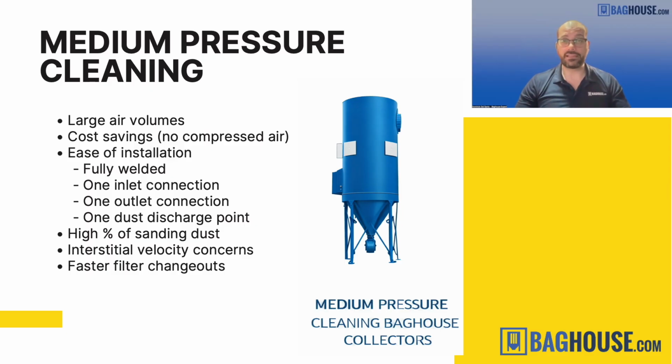Now, the second kind you might see is a medium pressure reverse air or reverse pulse baghouse. These are usually practical only at larger volumes, from about 10,000 CFM up to about 50, 60, or 70,000 CFM. These work by having a rotating arm that blows air back into the filters, and that cleans the dust off. They usually have a separate fan or a PD blower that supplies the air to clean it off. We call them medium pressure because they're usually blowing back in at something like 5 to 10 psi.